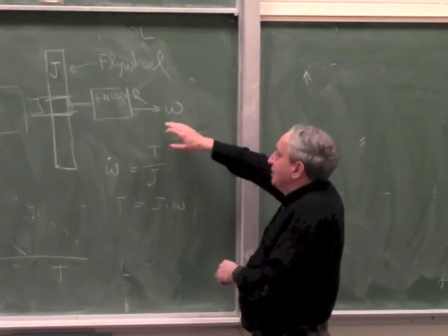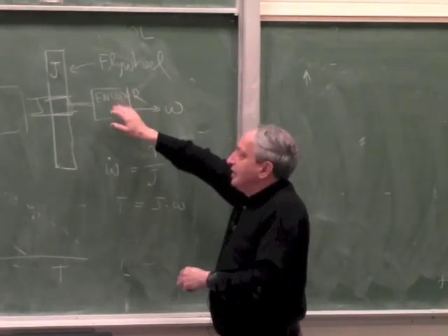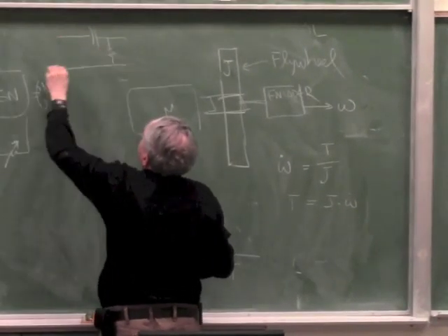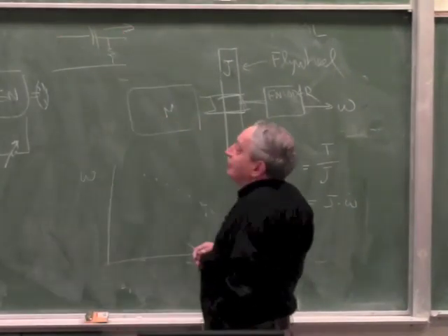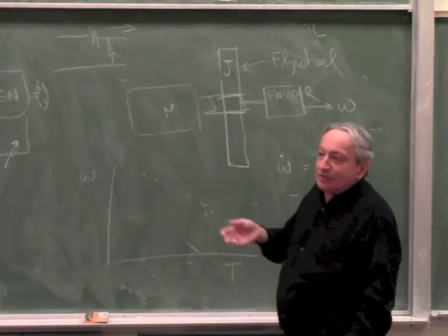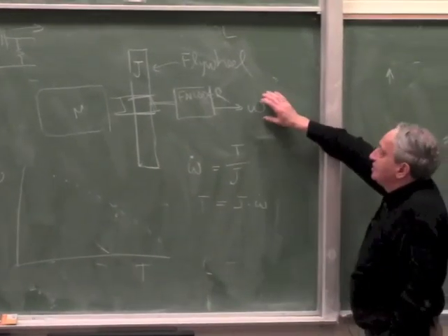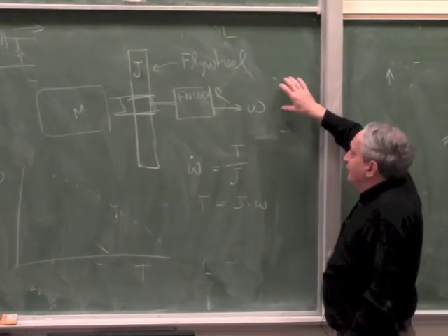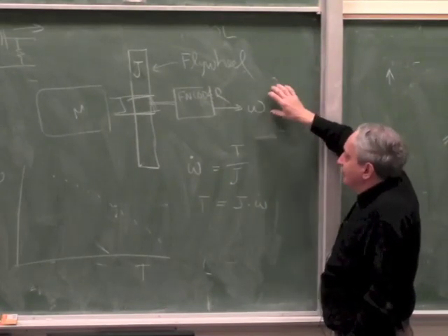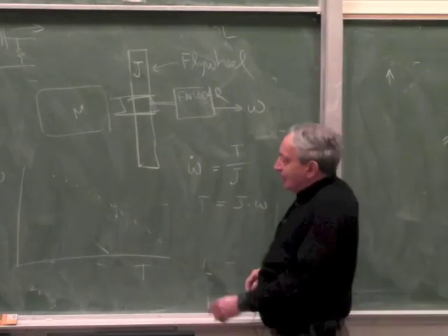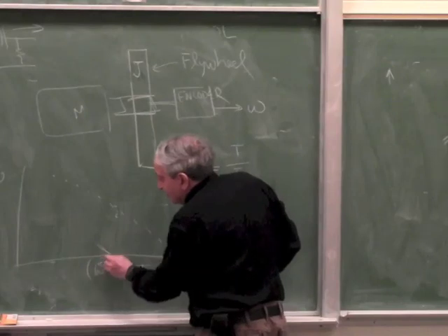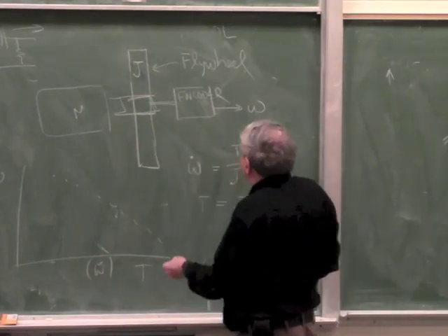If it was a DC voltage from a generator, I could just put a capacitor and a small resistor, and this will give me the derivative. With a computer, I can do it numerically. Let's say you convert this to a voltage. To make it simple, I feed it to a computer and I take the derivative, and then I get omega dot, or d omega/dt.